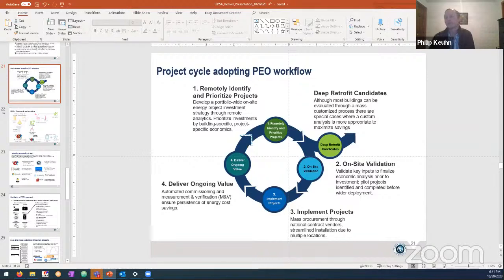I would also argue that there is a laundry list of other things you need to define about an HVAC system that have just as much impact as the load profile to that system. Obviously the performance curves, but also a whole laundry list of control strategies: supply air temperature, static pressure curves, things like that.